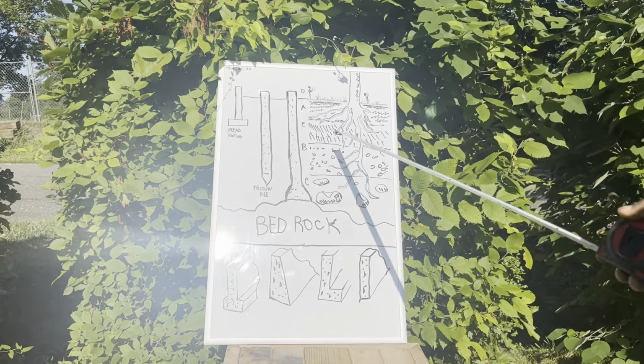And if you had soil, see this part of the top layer right here, you've got to put water on it first. Put water on it and then check it. If you rub it and it's gritty, then of course that's sand, okay? Also, if it's smooth, that would be an indication of silt, okay? And you know how gravel looks, but you can tell that this has a high clay content. How high, I don't really know, okay? But it's folding out into a ribbon, okay?